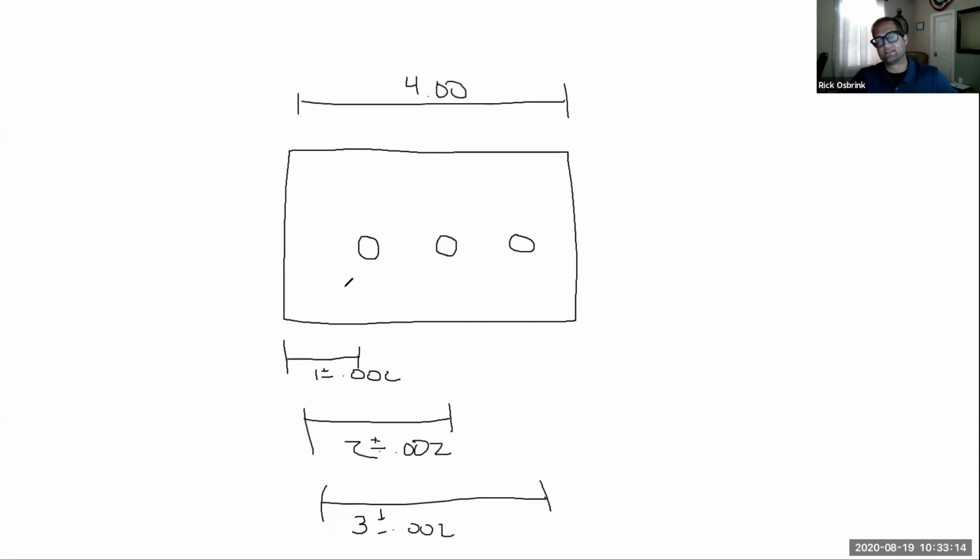What happens is, if I start stacking up tolerances, is if I don't use this one reference point. We'll call this side right here datum A, and it'll be annotated something like this, datum A. You notice how all of my dimensions are pulled from that one side right here: 1 inch out, 2 inches out, 3 inches out. This would be the right way of doing it.